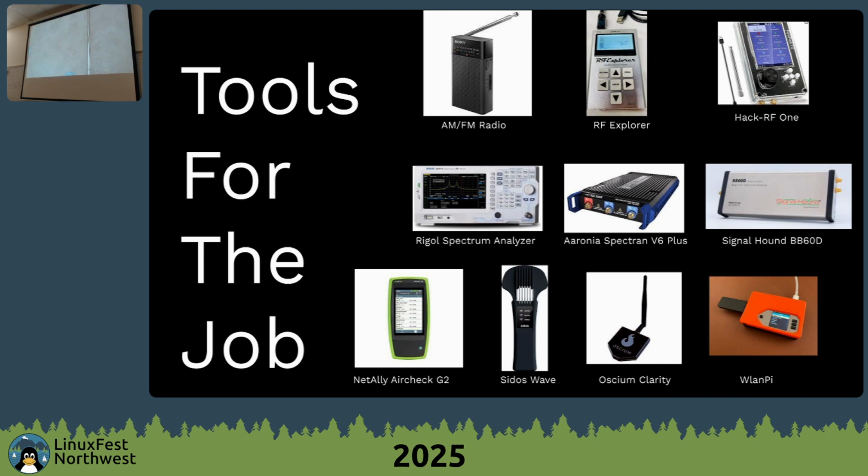And the PortaPack is also fun. If you get a PortaPack, you can install a HackRF into it. And so this is running some firmware that lets you do all kinds of things. You can transmit and receive. Here I'm just going to receive. You can pick up ADS-B, which is a transponder on an airplane, and it will show you the ident codes on the screen as airplanes fly overhead. And here I have the audio set up, and I have it tuned to a radio station, and if you put it in wide FM, you can hear the radio station because it can demodulate the FM radio signal. And so that's what it looks like. So I'll let you guys play around with that as well.